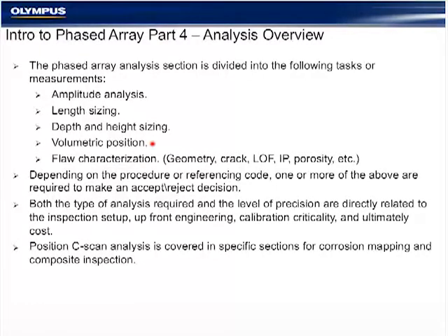The location or volumetric position is normally our number 1 indicator, next to A-scan characterization and two-sided detection, for telling us what type of flaw it is, meaning porosity, slag. In a typical V-weld, all of the different types of failure mechanisms, lack of penetration, inadequate penetration, and so forth. Again, volumetric position is our key indicator.